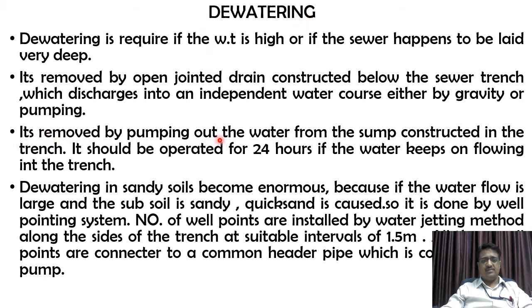It is also removed by pumping out the water from a sump constructed in the trench. We can construct a sump there, and it should be operated for 24 hours if the water keeps on flowing into the trench.